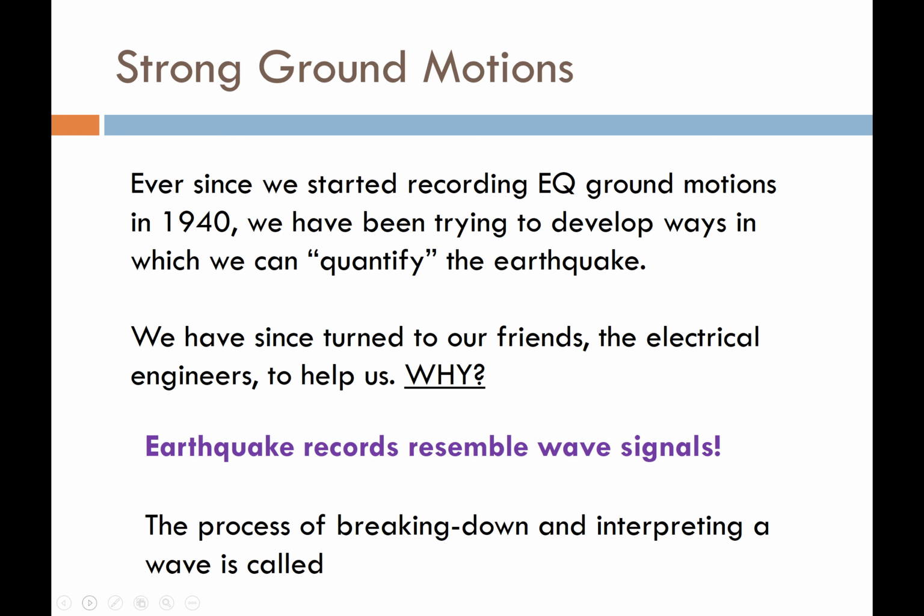And earthquake ground motion recordings resemble wave signals, and so we can take some of the principles and things that they apply on a regular basis and apply those principles to earthquake waves. So the process of breaking down and interpreting a recorded earthquake wave, or any wave for that matter, is called signal processing.